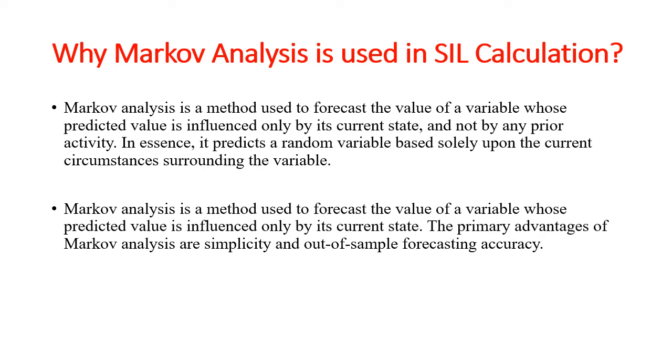If you see any SIL loop, normally the behavior of the SIL loop depends only on its current state, not on what happened before, maybe one year before. That does not really influence it. So that is one of the reasons for using Markov analysis in SIL calculation.